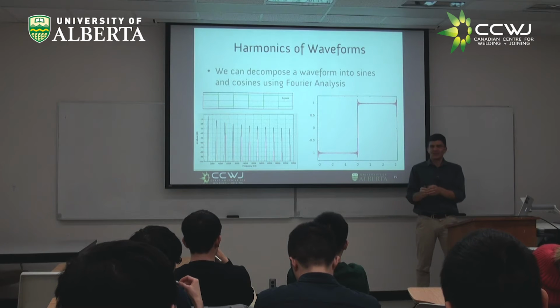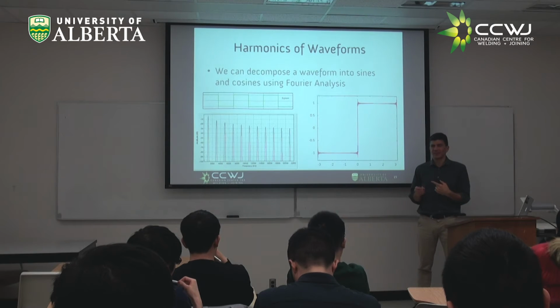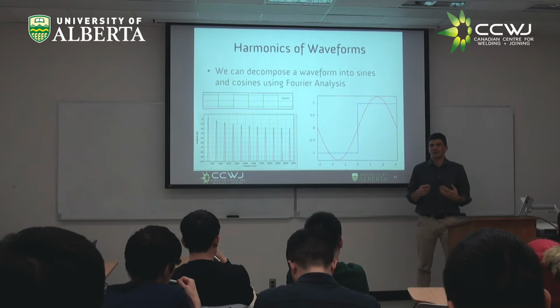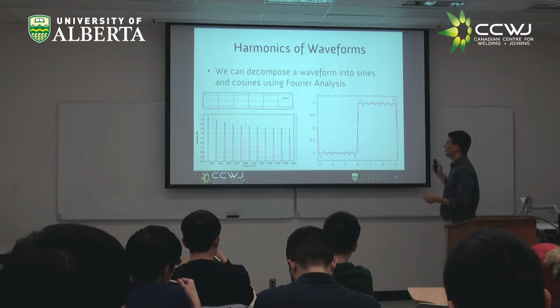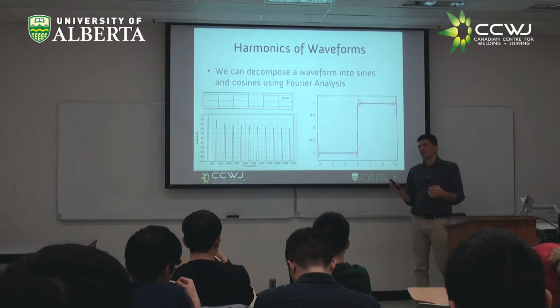Right? 6010, you can use, works only on DC machines. 6011 is more stable, works on AC, right? Now, you start to see how things go, right? Like, OK, now, if you are going to use